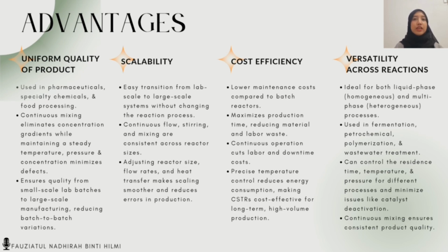Next is cost efficiency, where the CSTR has lower maintenance costs compared to a batch reactor. It also maximizes the production time and reduces material and labor waste because of the continuous operation. The precise temperature control reduces energy consumption, making this reactor cost effective for long term and high volume production.